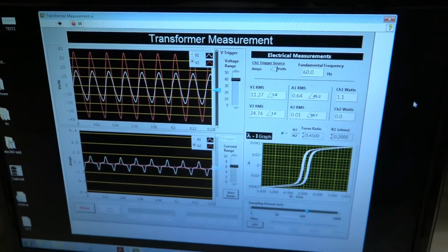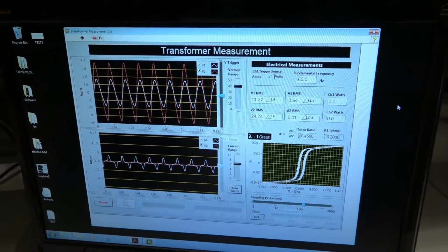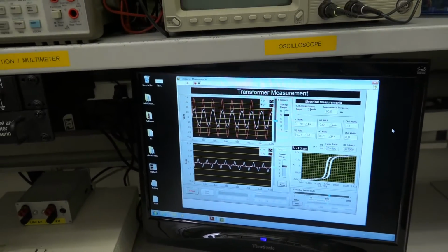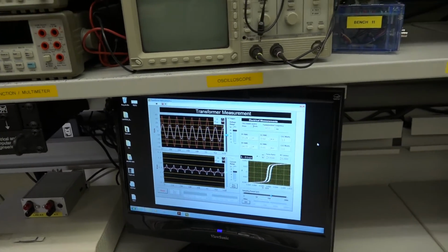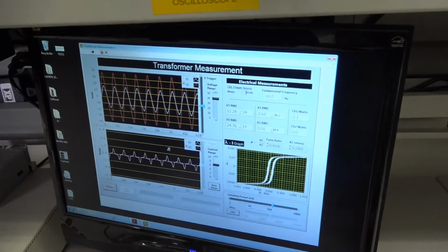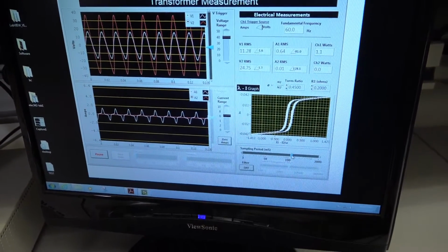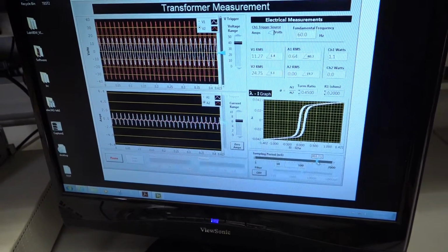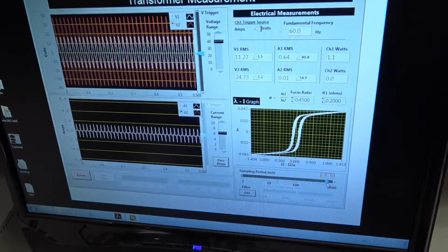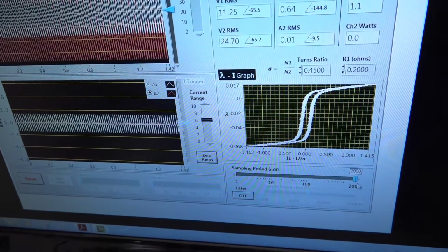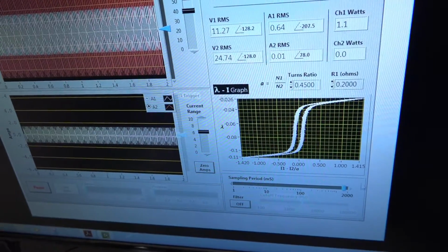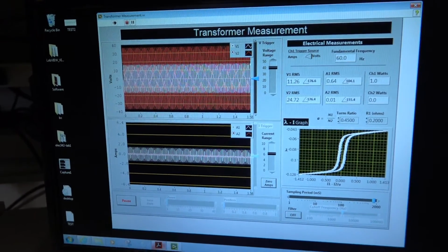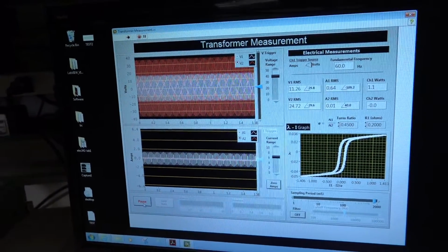As you can see, we have nearly 120% of our nominal voltage on the primary side. Now, to be able to capture the transient on the primary side when we are going to connect the voltage, I will increase the capturing window to nearly 2 seconds so that I will have enough time to pause my measurements when the transient happens.